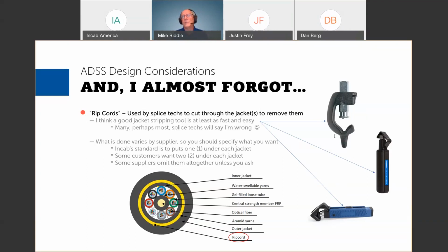However, lashed cables, especially on high voltage lines, remember I talked about the number one killer of ADSS in the field was shotgun damage. And so some people have tried to get clever and used a lashed armored cable, a corrugated steel armored cable, on a transmission line. And then they thought, well, at the splice points we'll just ground it.